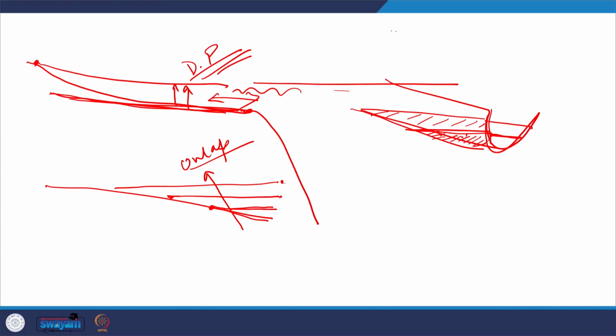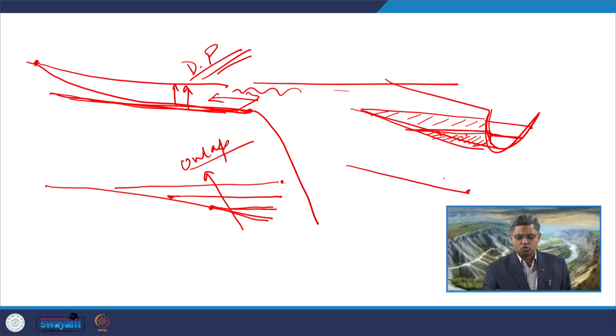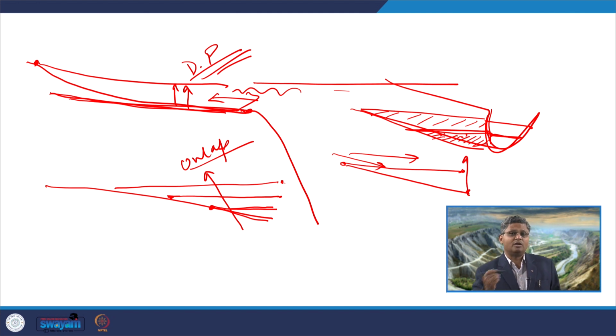So, as the river slope gradient is changing, it is decreasing, it will induce a lowering in the fluvial energy with time. As gradually the lowstand condition is progressing, we will get more decrease in the fluvial gradient system. So, when we are looking at a river system which was initially here, the flow which was going on over here will have more energy. Now, if the river gradient is changing like this, the energy of the river will decrease. So, this decreasing pattern in the river energy condition will be more prevalent in this area.